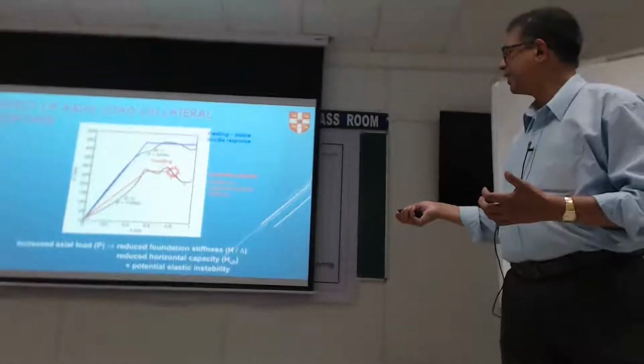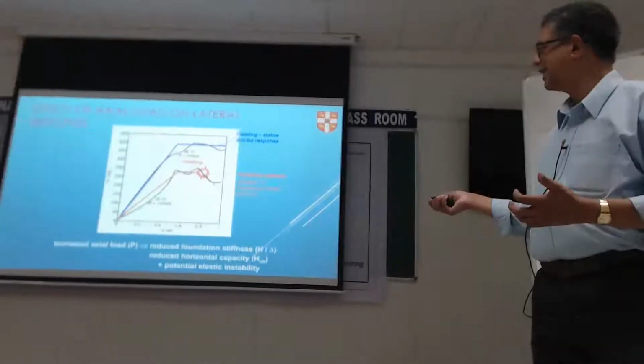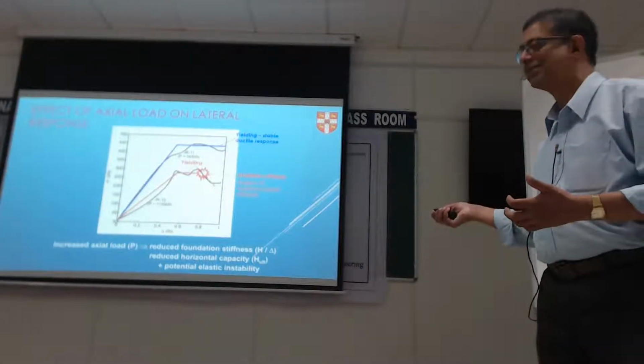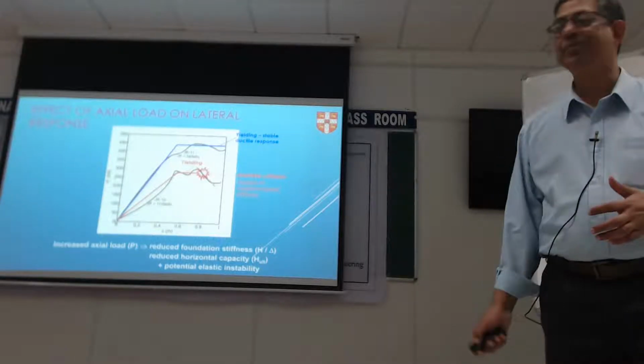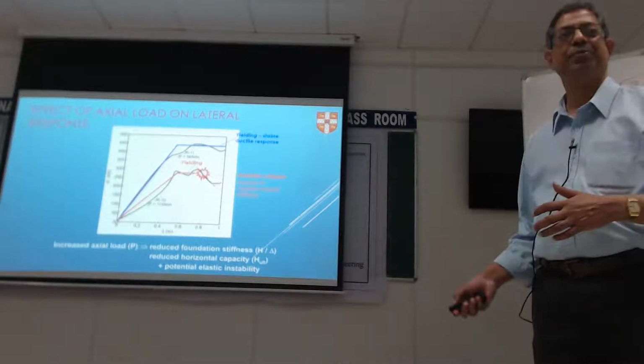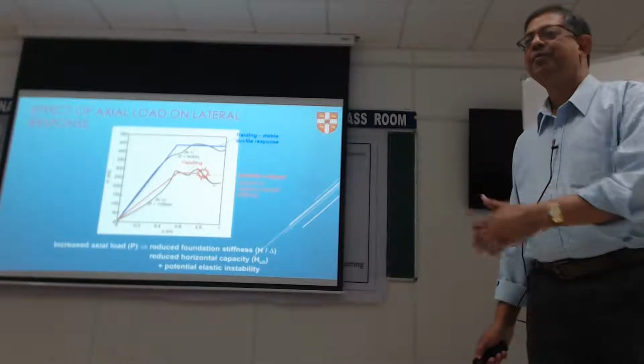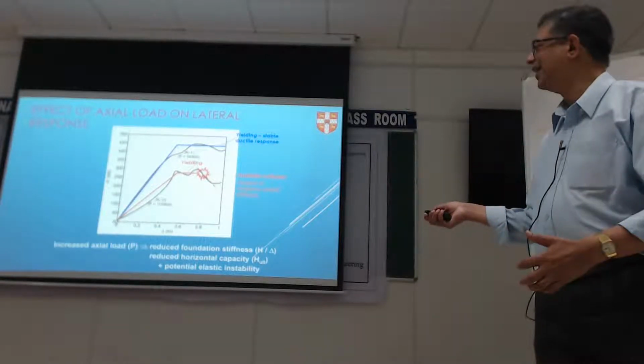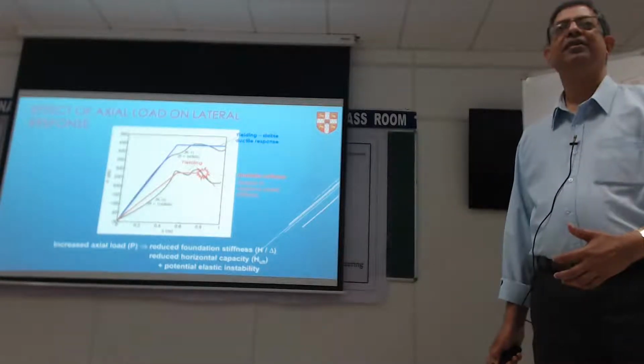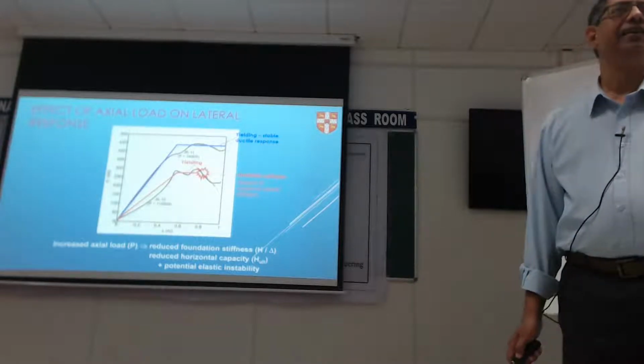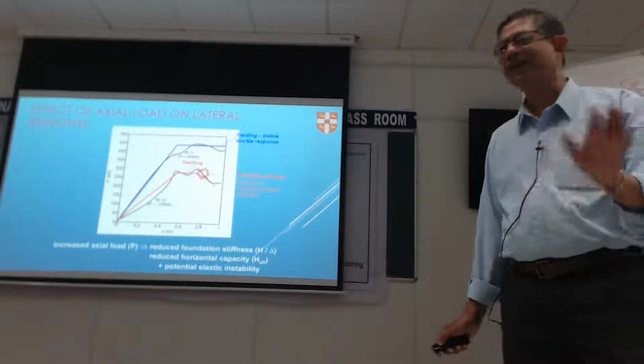So the fact that my experimental line went up to there, stayed a bit constant, and then tried to go down the slope is not good. That means I'm going to accumulate a large horizontal displacement with a dropping horizontal load. That's deadly. That means you're not going to recover from that. Your pile group is bye-bye.